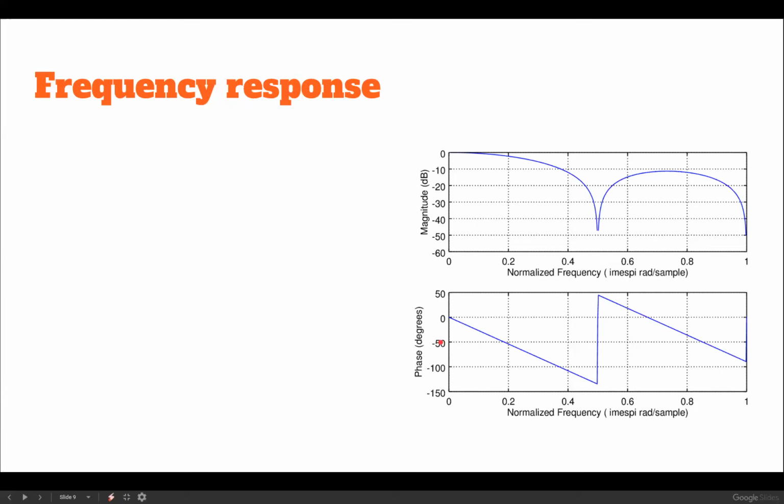And it looks like that. This is actually the 4-point running average filter, magnitude response and phase response on a normalized frequency axis, meaning that this is the 0 frequency and this 1 is the same as phase angle pi, meaning the sample rate over 2.